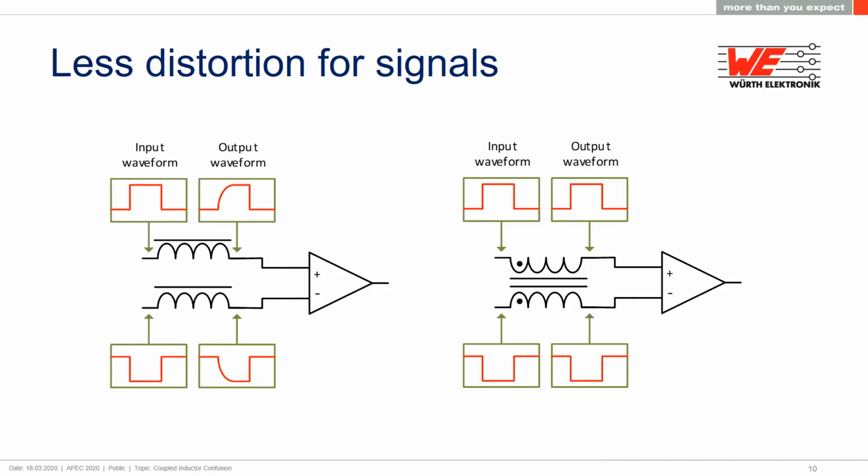Here's another advantage of common mode inductors used in differential signaling, which you see a lot of today. Most high-speed serial interfaces use differential signaling. If you were to use individual inductors on each of the differential lines, you would end up making yourself a filter, and that filter would round off the edges of the signal. By using a common mode filter, the fluxes of the 2 differential signals cancel each other, and any common mode noise would be attenuated, so it's an advantage. You're using 2 windings on the same core to influence each other and produce a better result, better signal integrity.